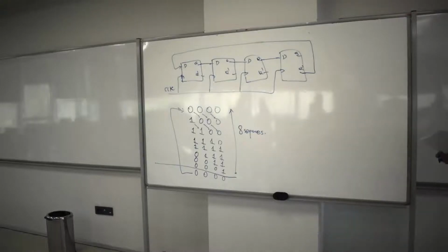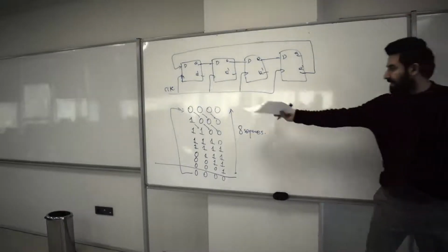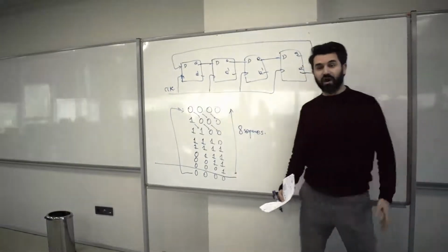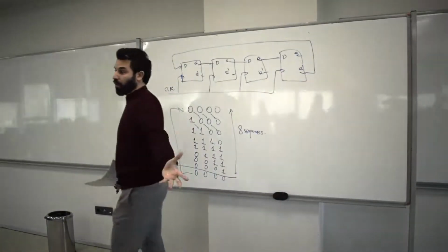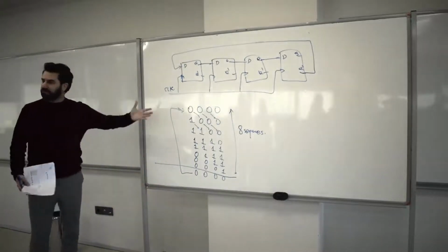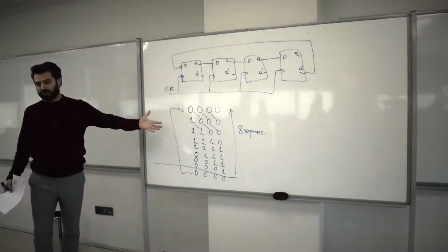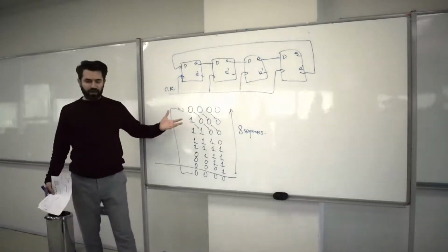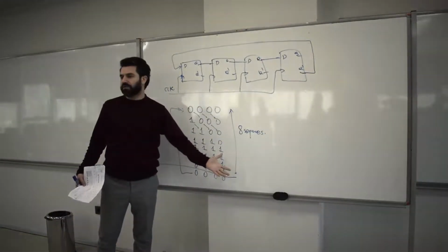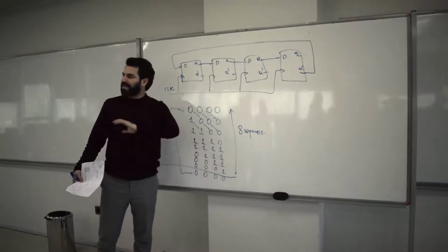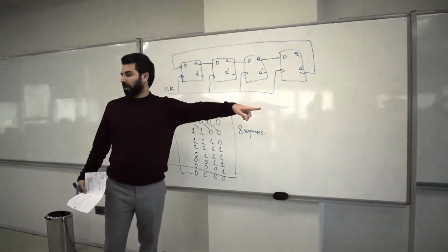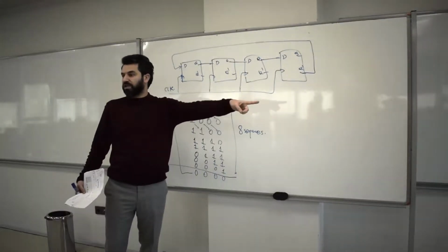In order to make the output resemble the format that I just described, because that's going to be useful from a hardware perspective, then I have to apply some gates here, unfortunately. Okay? That's the pitfall of having 8 sequences. Without any gates, there's a limit. That's 4. You can't go beyond 4. And that's the ring counter. That's what the ring counter gives you.